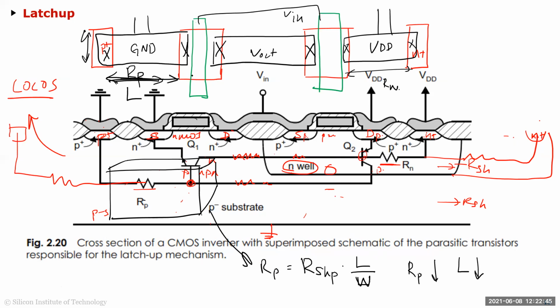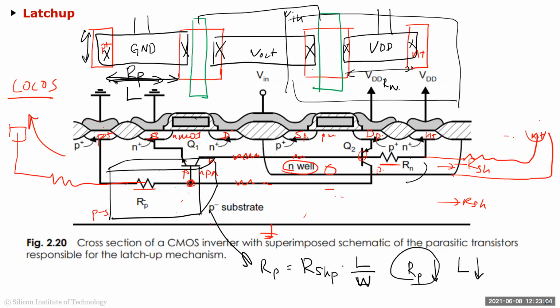So in other words, when you're laying out, you want to make sure that you have a substrate contact either to your P sub or to your N-well. So this is your N-well contact, right? You would have drawn N-well and drawn the N-well contact as close to the source drains of your active devices as possible to minimize these two resistances. If you have this far away, once you get your chip back, probably it'll latch up and just burn the whole chip.